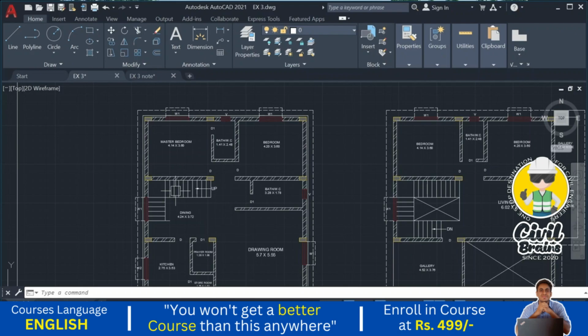I will show you here: the walls, the column positions, the doors, the window positions, and the projections of the slabs, chhajjas and all. These should be there in any plan. Beyond that, we know there are furniture plans, electric plans, plumbing plans, site plans, everything. But these are the minimum criteria which should be there in the presenting plans.